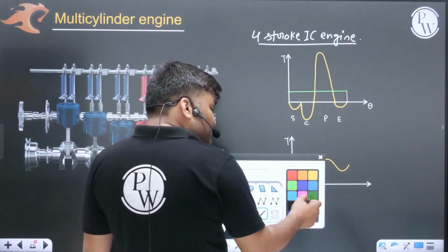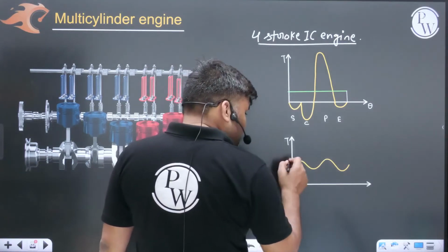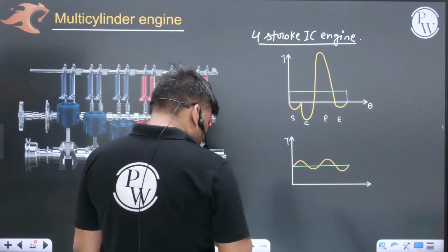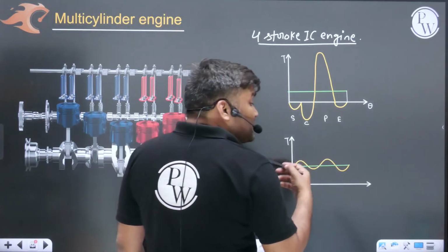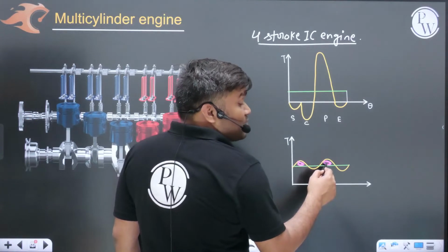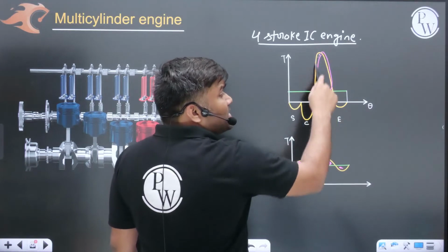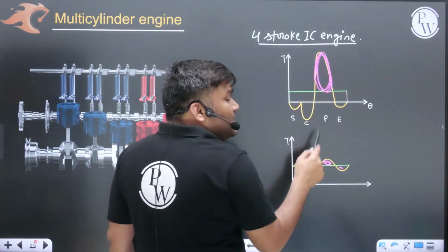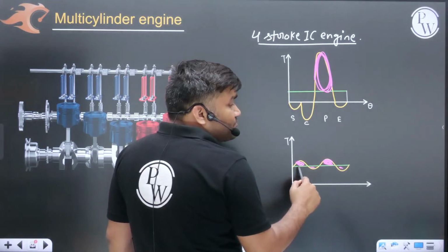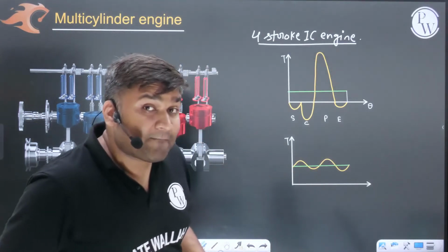Now, if you take the mean torque and resisting torque, the mean torque is somewhere here. This is the mean torque. Same resisting torque is there. Now, can you see what the fluctuations are? Now, fluctuations are very, very small. In this fluctuation the flywheel will absorb energy. Here the flywheel will deliver energy. Imagine, earlier this amount of energy the flywheel had to absorb. Now the flywheel has to deal only with this much amount of energy. Can you feel? Sir, the energy fluctuations are less, so the flywheel size will also reduce.